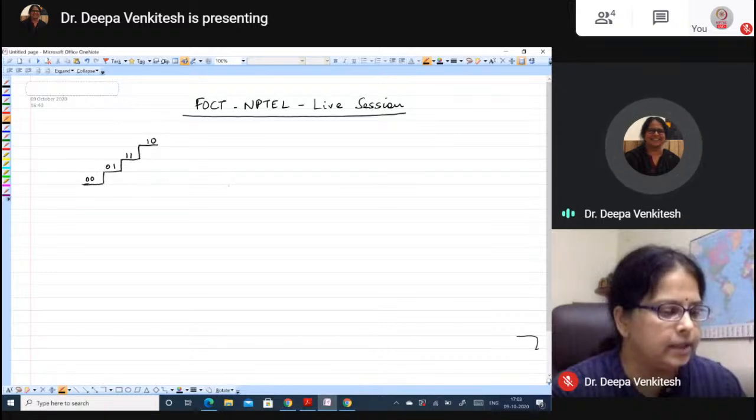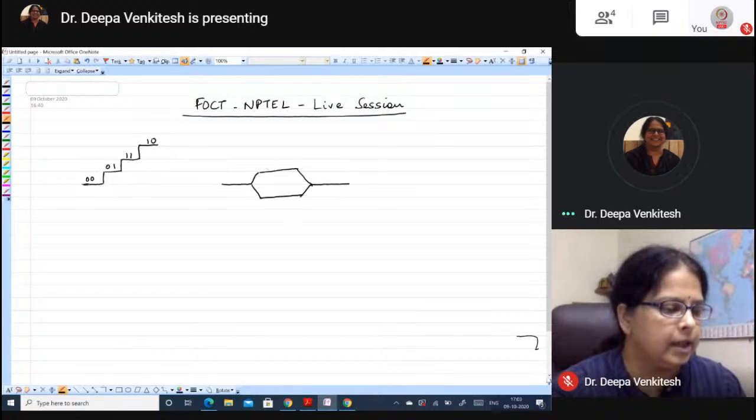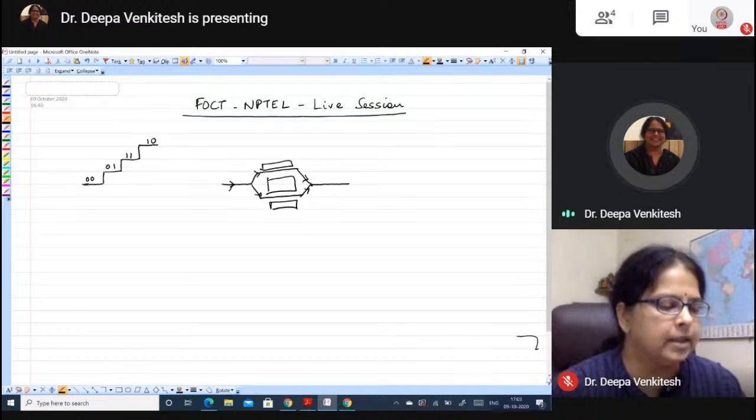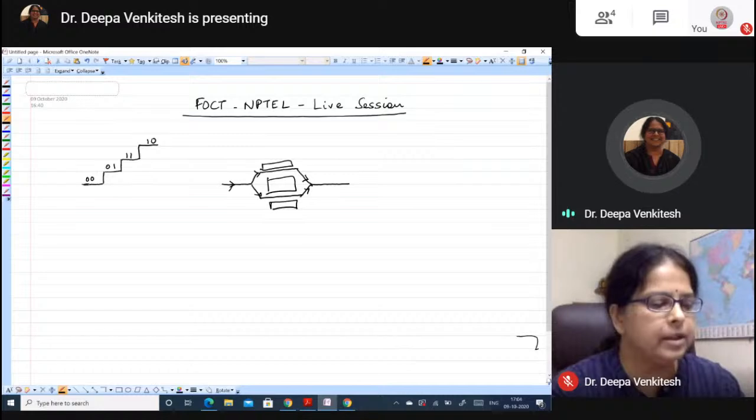You saw that if you take a Mach-Zehnder modulator, and let's say you are taking a dual drive modulator, you have an electrode in the middle and then an electrode here. You send your light in, it splits, and then it combines. In a dual drive modulator, we said that we give a voltage only half of that required for a single drive modulator.